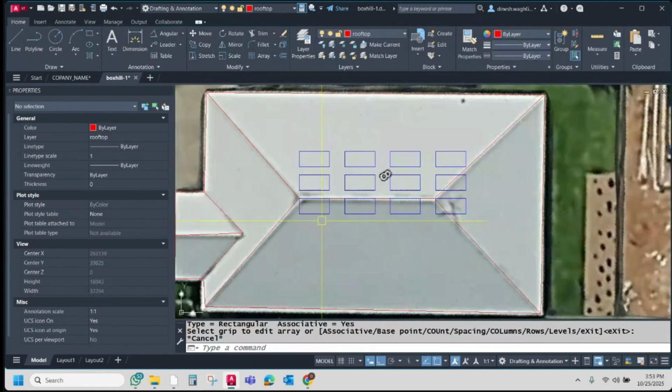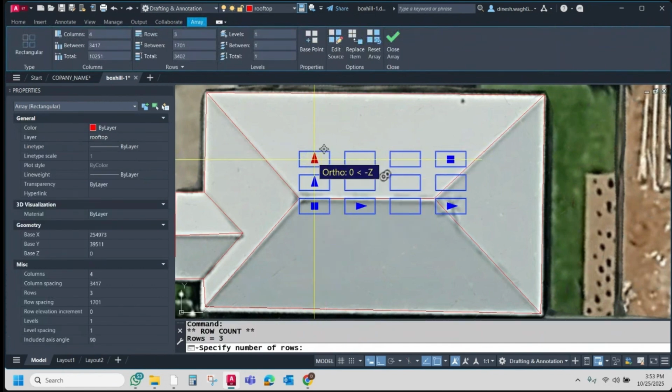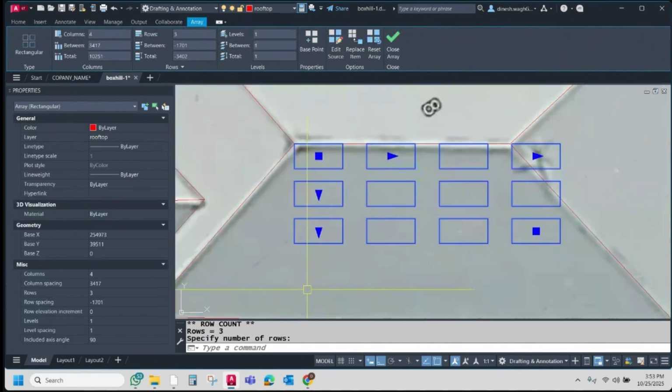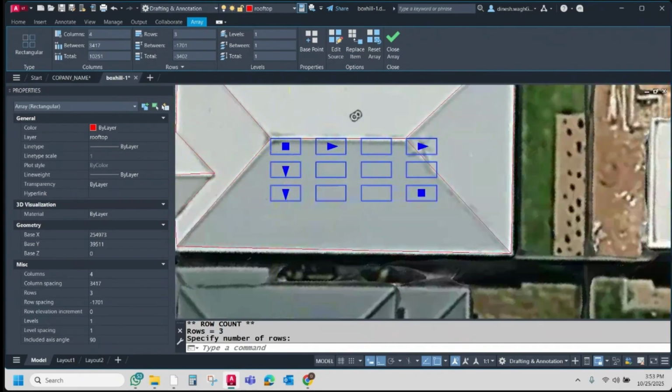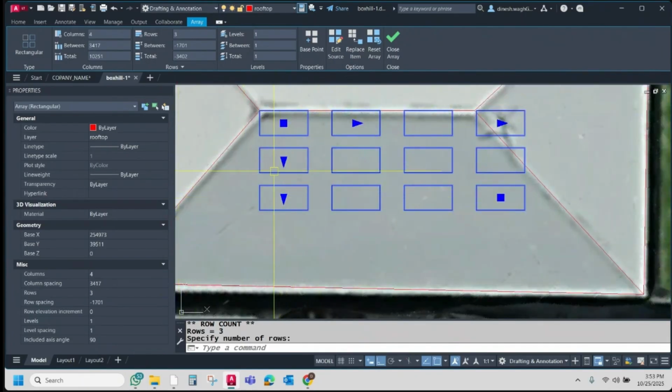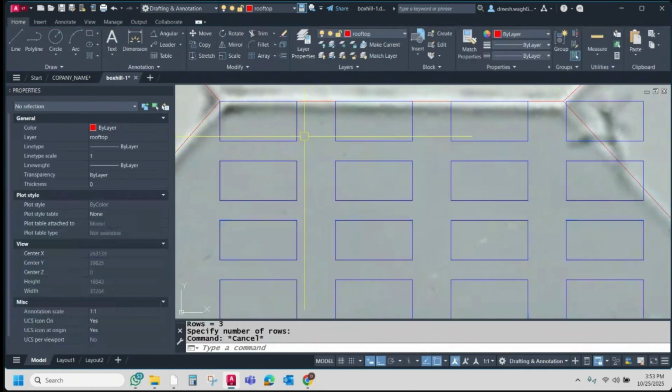So now we can see here are three modules and four modules in the array, but we want to draw toward the bottom side, meaning south side. So I just select this and drag from this point to the bottom side, south side. So usually normally four modules are there, so four modules. Okay, then we need to specify a 20 mm distance in between these 2 points and these 2 points, which is where our frame needs to place mid clamp, end clamp, everything.